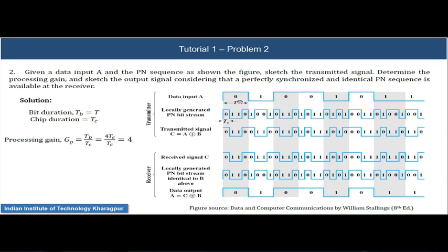Now when we are given binary data, we XOR the input data with the PN sequence data in order to get the output spread signal, and as we can see, the input data XORed with this PN sequence gives us the spread transmitted signal.